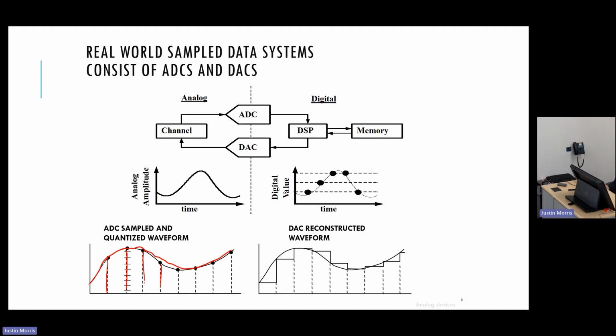And then in order to output this same thing, we would need to use the digital to analog conversion. And again, we're in discrete, so we can't output continuous. So it kind of becomes like for that set period of time, it's this one set value that approximates the curve. And then for the next step in time, it's the next value that it should be, but it just doesn't change during that time. And we keep doing that. So we get this approximation of the output as well.